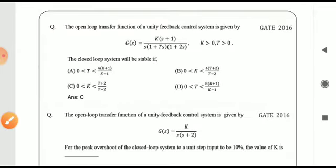Okay, now coming to the next question. The open loop transfer function of a unity feedback control system is G(s) = K(s + 1) / (s(1 + Ts)(1 + 2s)) with K > 0 and T > 0. The closed loop system will be stable if... again, we can check stability by using the characteristic equation of the system.